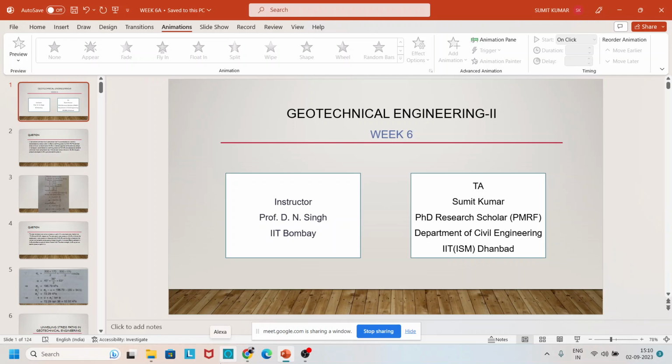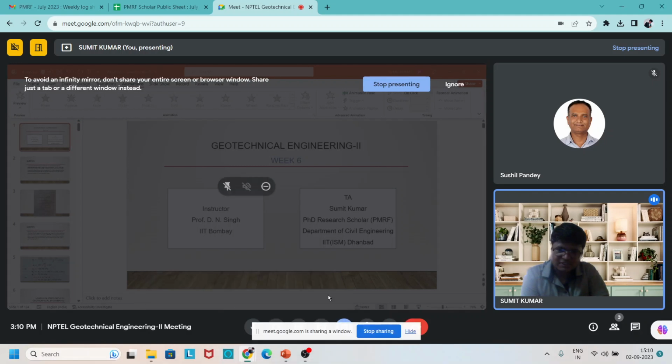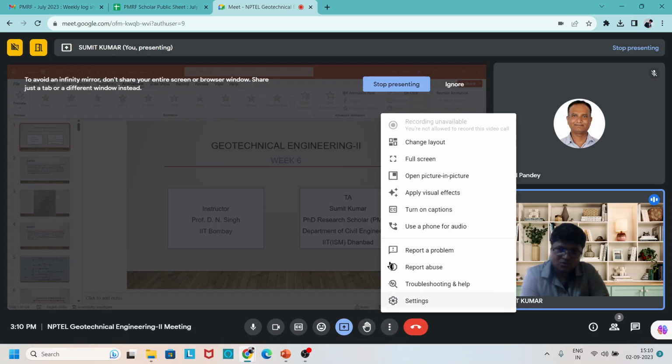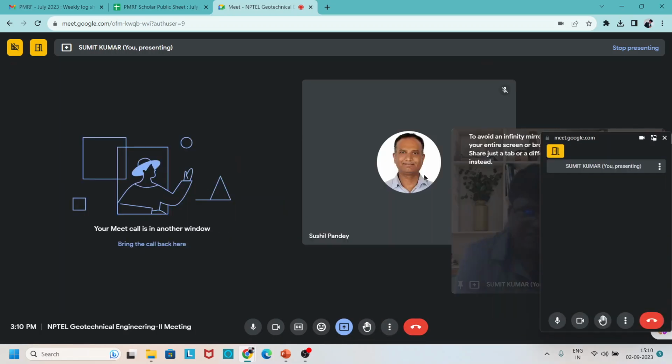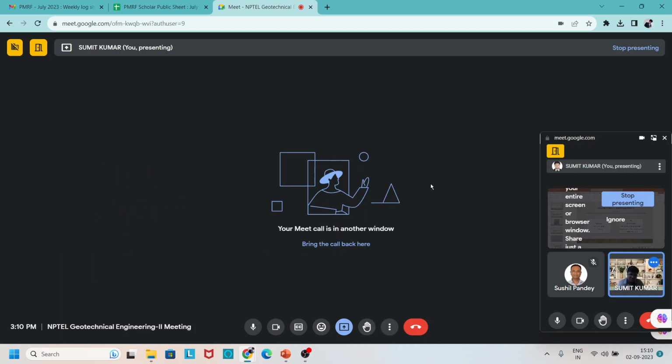Apart from that, we are also going to study approaches like the stress path, as we have already understood the meaning of sigma 1 and sigma 3, when we apply the confining stress, and what happens when we take those concepts during the second stage. Those things we will take into account during this session.